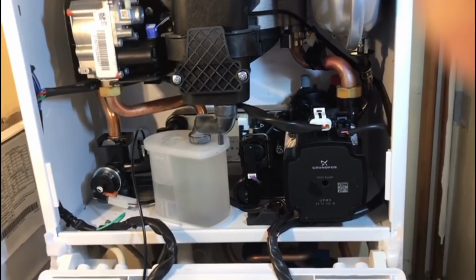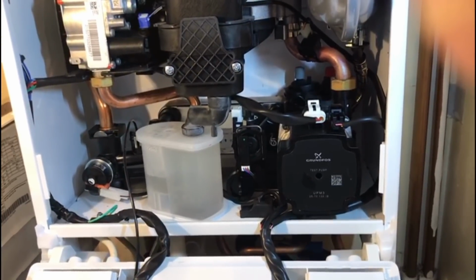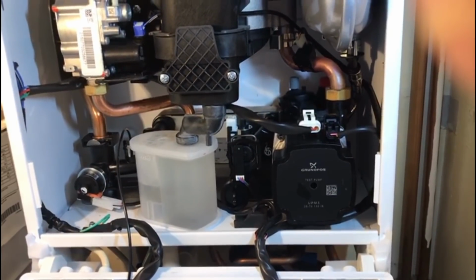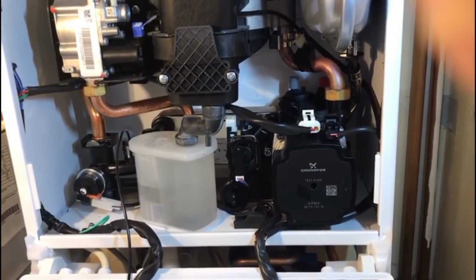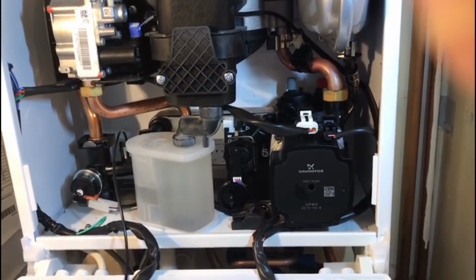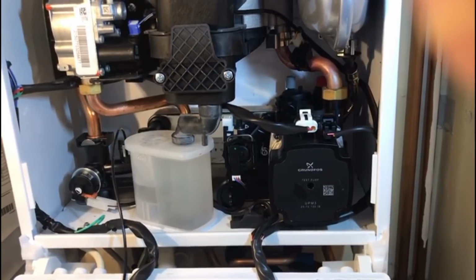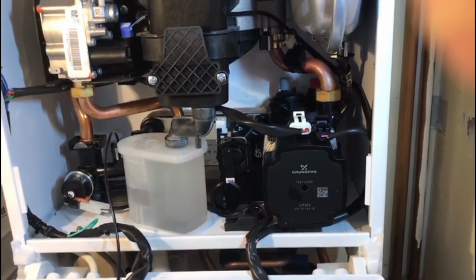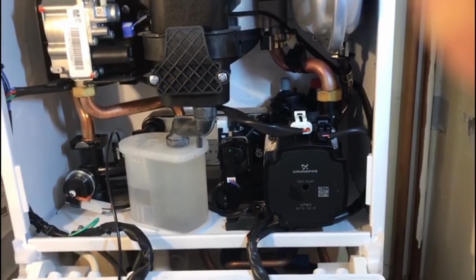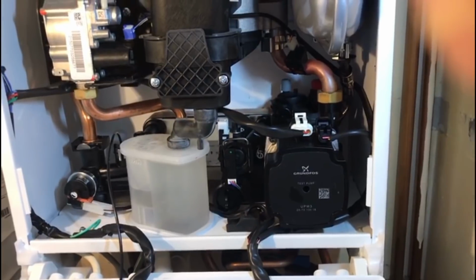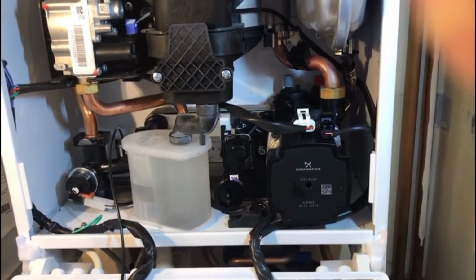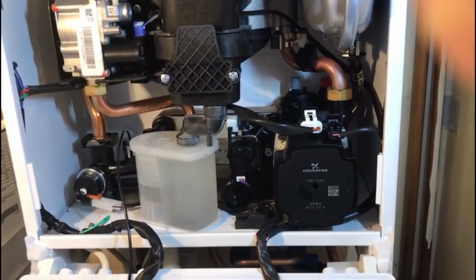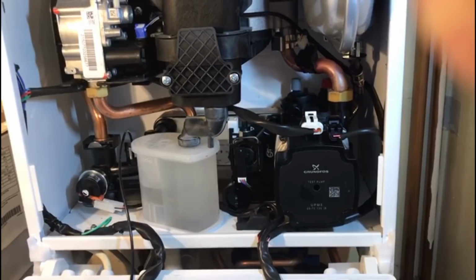Granted, I will say that with experience, you can probably diagnose the fault as being a restricted plate heat exchanger 9 out of 10 times with just the symptoms alone, but there will be the odd occasion you will be wrong. And I've watched a couple of YouTubers show that when they're on the job they've diagnosed the blocked plate and remedied the issue, but they've never shown you how they've tested to confirm that this was the case, and that's what I'm going to show you today.